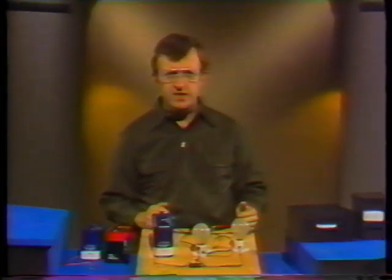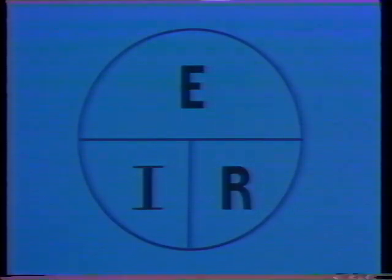We've shown you how to represent Ohm's law as a formula for figuring out what current should be. We can also rearrange the formula to figure out what either voltage or resistance should be when the other 2 values are known. Going back to the circle, you can see that we can find voltage by covering up the E. E equals I times R. We can find resistances by covering up the R. R equals E divided by I.